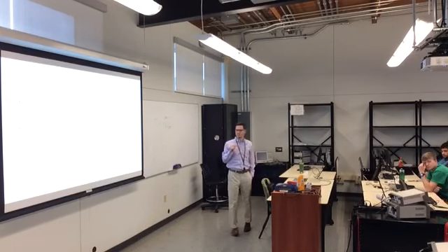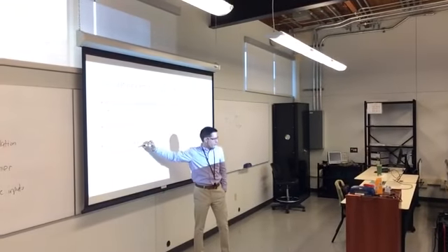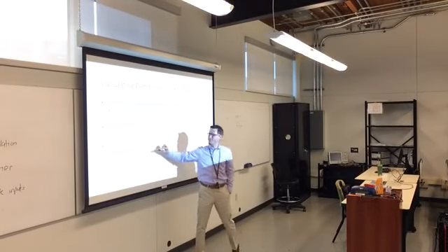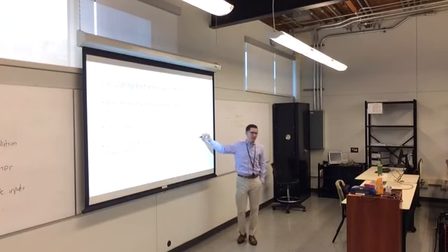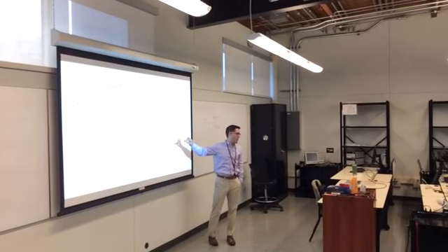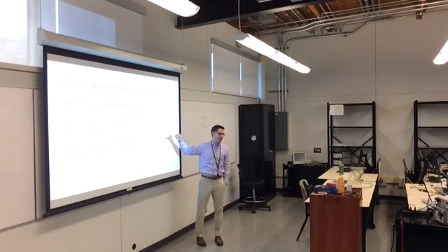All right? Do this real quick. Assuming you've got a 16-bit counter, it operates naturally at 25 megahertz, but you're going to scale it by 512. What is the maximum amount of time that can be counted with that system? So take a minute, do the math on that one.